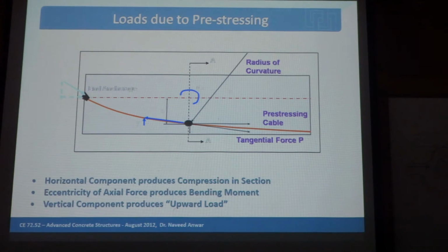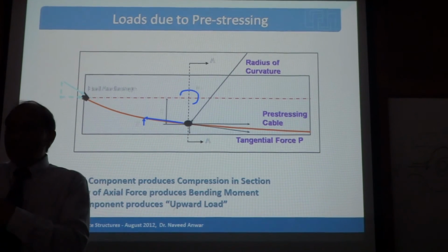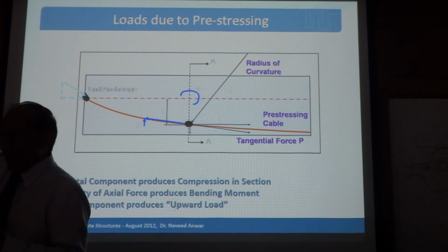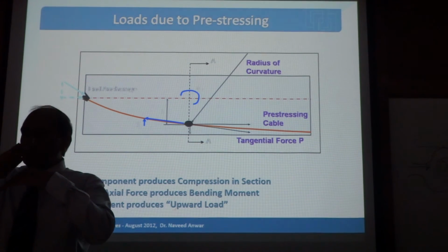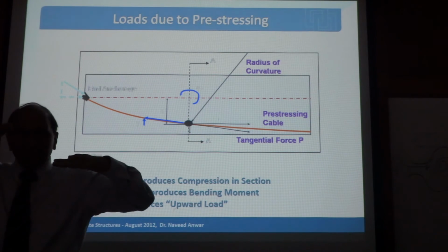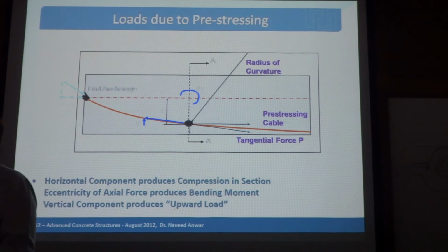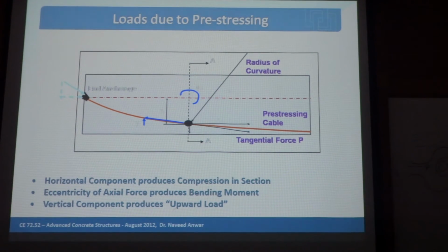So this cable is not only a pre-stressing inside the beam, it is also a member with an incline, with the force which is inclined, having a resultant horizontal and vertical. Horizontal component puts pre-stressing, vertical components create a vertical force onto the beam.